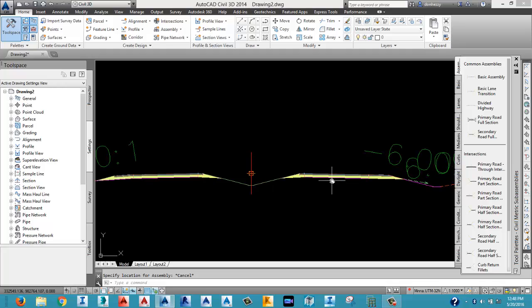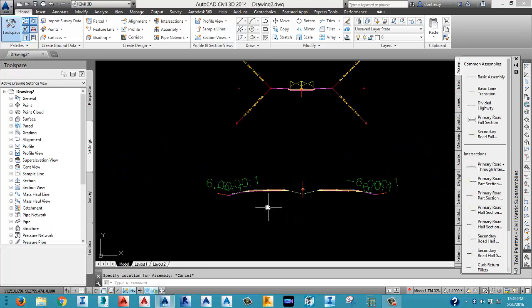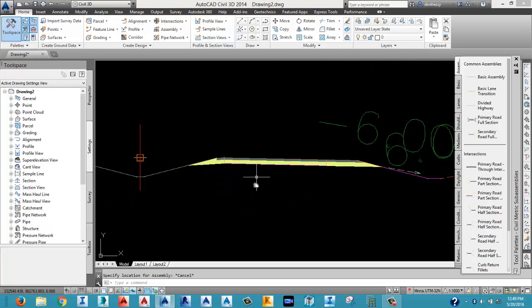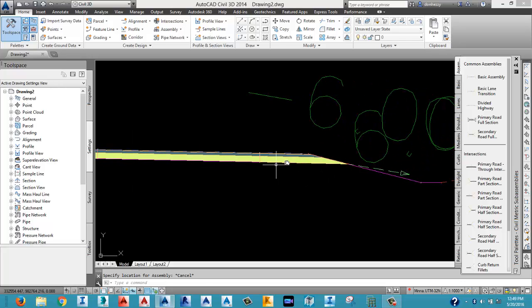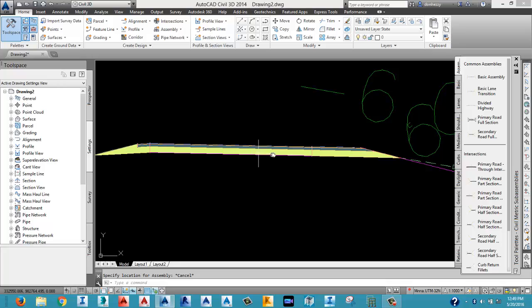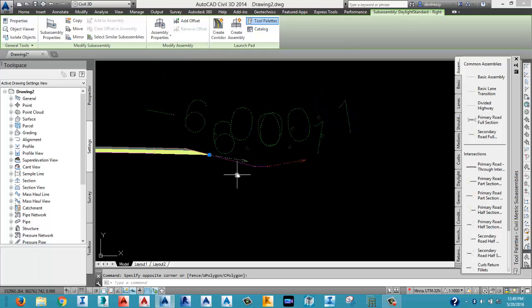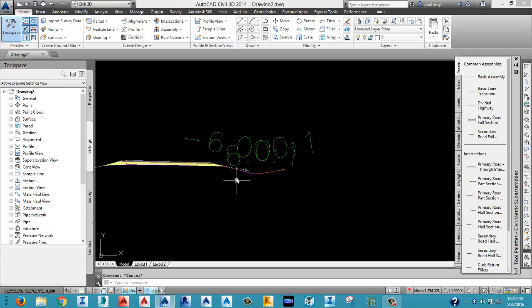So you can see the divided highway. This looks like a typical express road, whereby apart from the service lane, which is not included here, you can see how it looks. You have this typical road, and at this point here we have shoulders. We have a lane, then a shoulder, then this daylight parameter, which is either your cut or fill, depending on the daylight condition. Whenever it sees any area that it needs to cut, it cuts. Whenever it sees any area that it needs to fill, it fills.